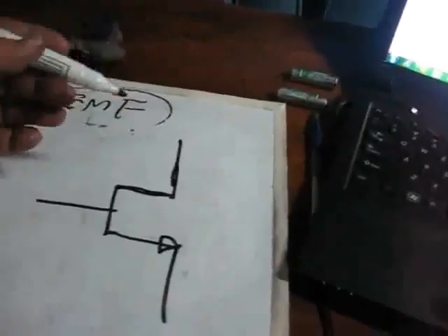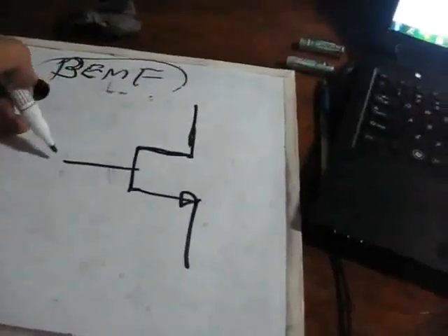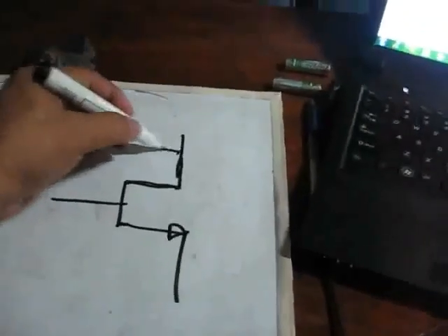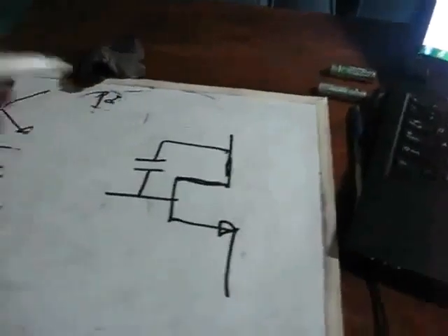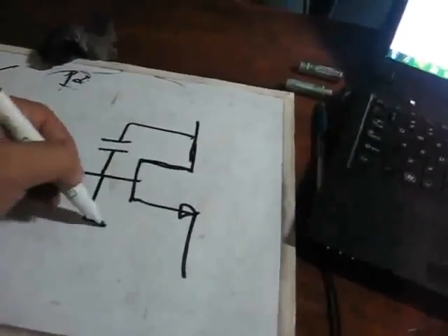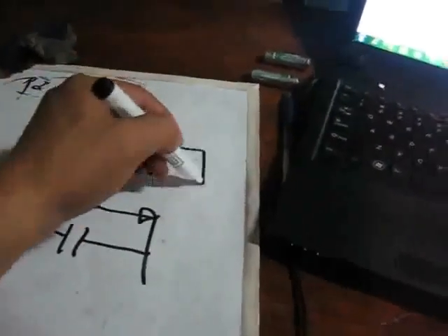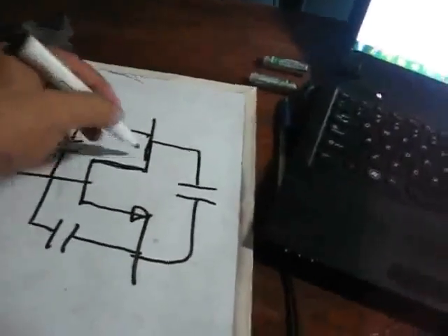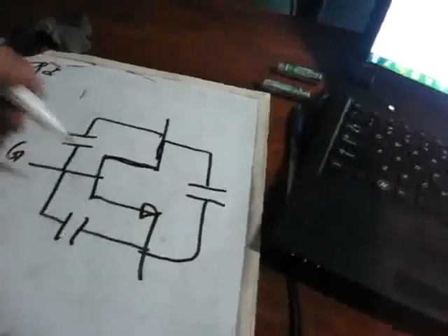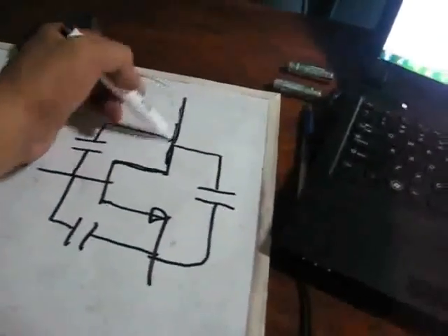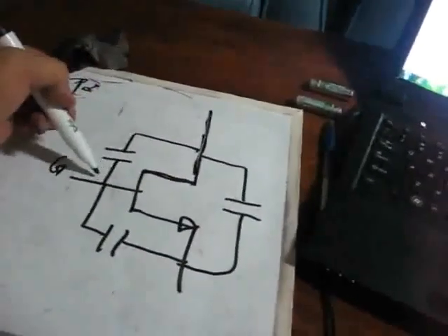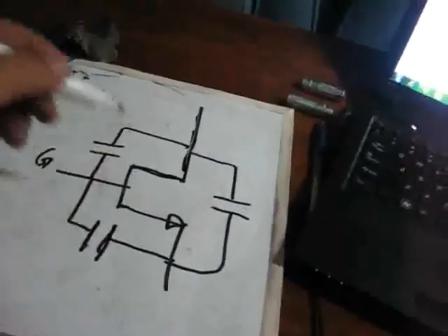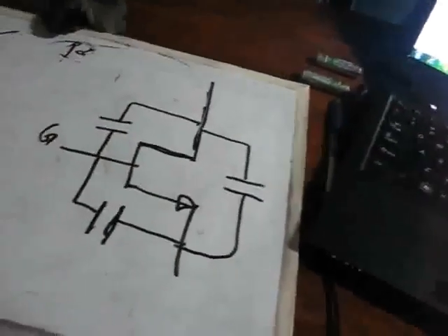If you go to the ambient, it's a high static thing, high voltage, high static. This IGBT starts to create, it's like a capacitor. They have a built-in capacitor. They call it parasitic or whatever, but this one becomes capacitance. This area from the gate, source, drain, that's the problem, because with this wire, if you are connecting here, this is like an LC already, and then parallel and series LC. So this is a problem.